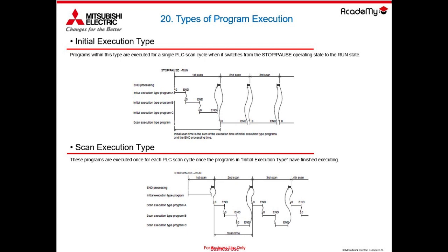So in this case there are three programs in a priority order based on the order established by this little button, this little window up down, based on this execute order. The execution is continuous between programs A, B, and C. In this case, A has priority over B, and in turn B has priority over C.